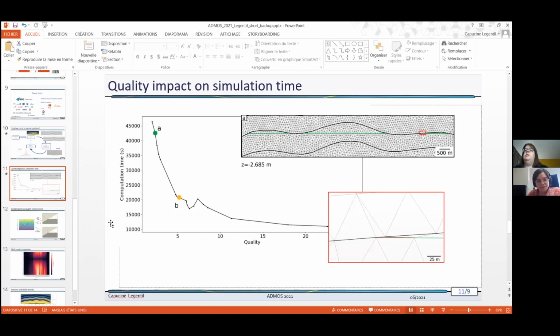So the main challenges of my work are to maintain the conformity all along the boundaries and the inserted lines, and to keep mesh quality quite good to keep a simulation time reasonable. And what is reasonable in this particular application context? With my computer, that has just 4 cores, a reasonable time is 6 hours maximum.